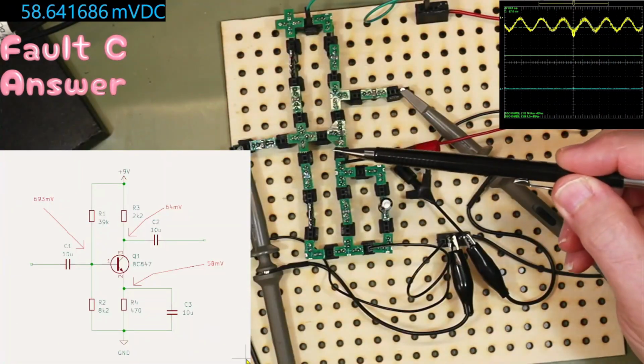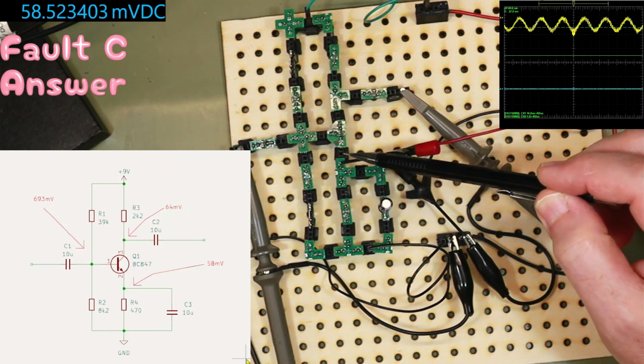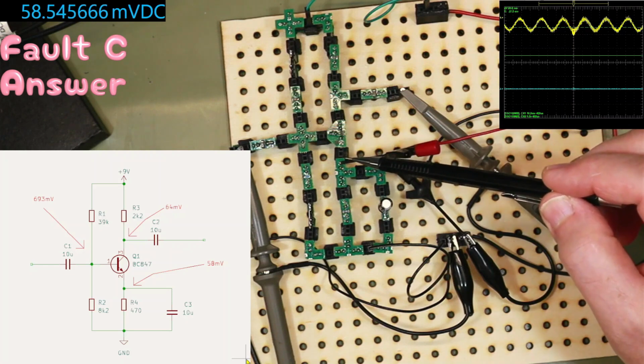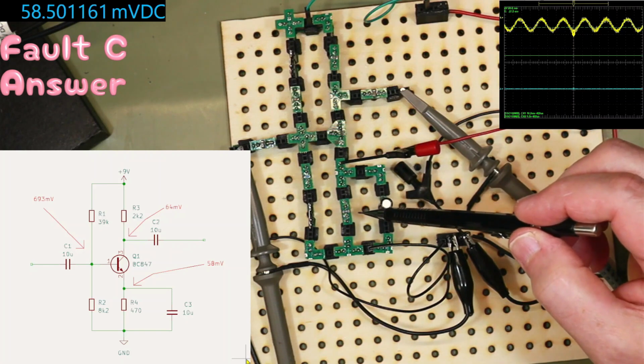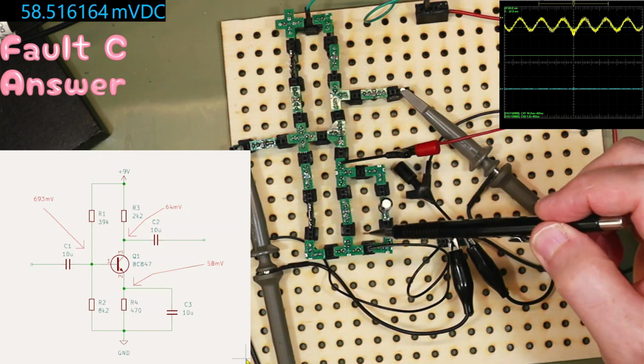We have about 600 millivolts base emitter, so this transistor is kind of biasing itself, but we have no current, no voltage drop across the resistor, the emitter resistor. It's 470 ohms, so that means there's no current flowing down here.